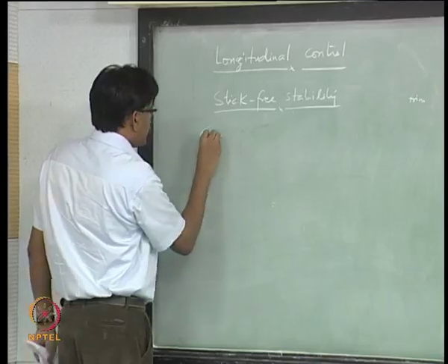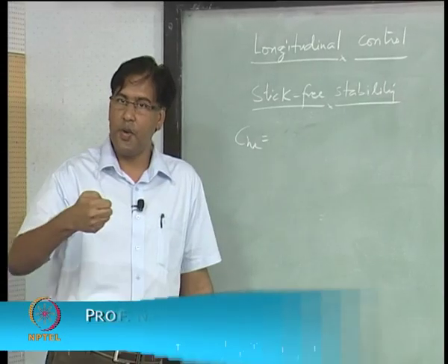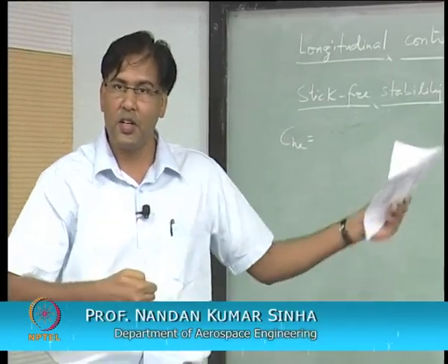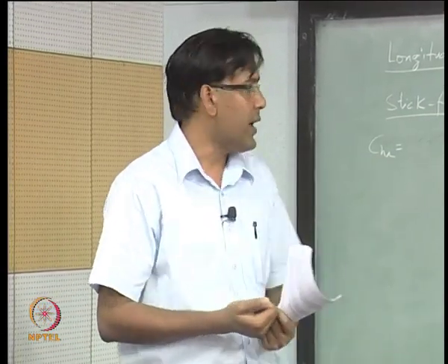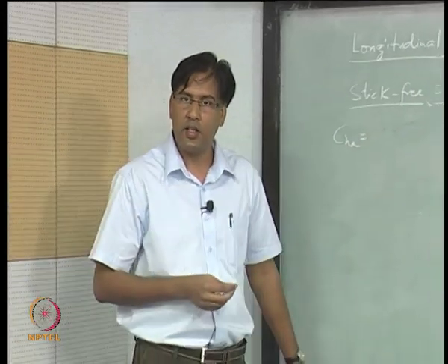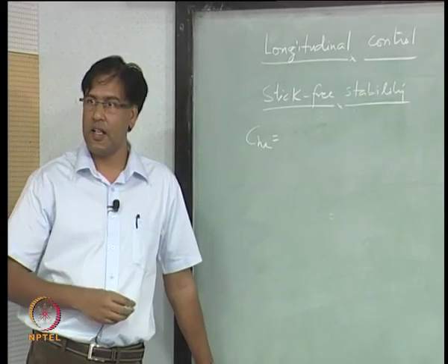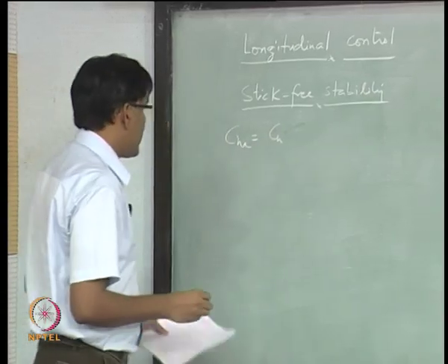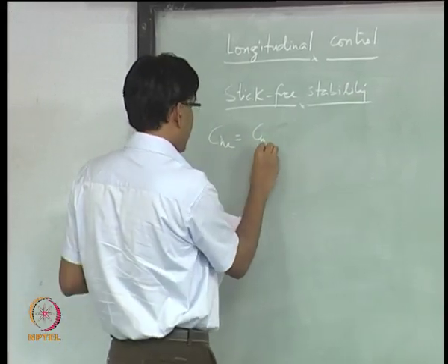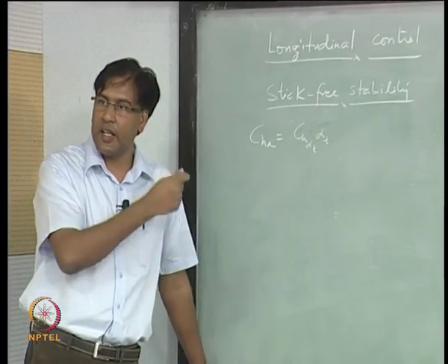So this hinge moment coefficient is going to depend on, hinge moment is the aerodynamic moment that is coming over to this small flap, right, that has to be overcome, right. What is it going to depend upon? Angle of deflection, angle of attack, right. So C_H depends on alpha_t, the angle of attack at the tail, right.